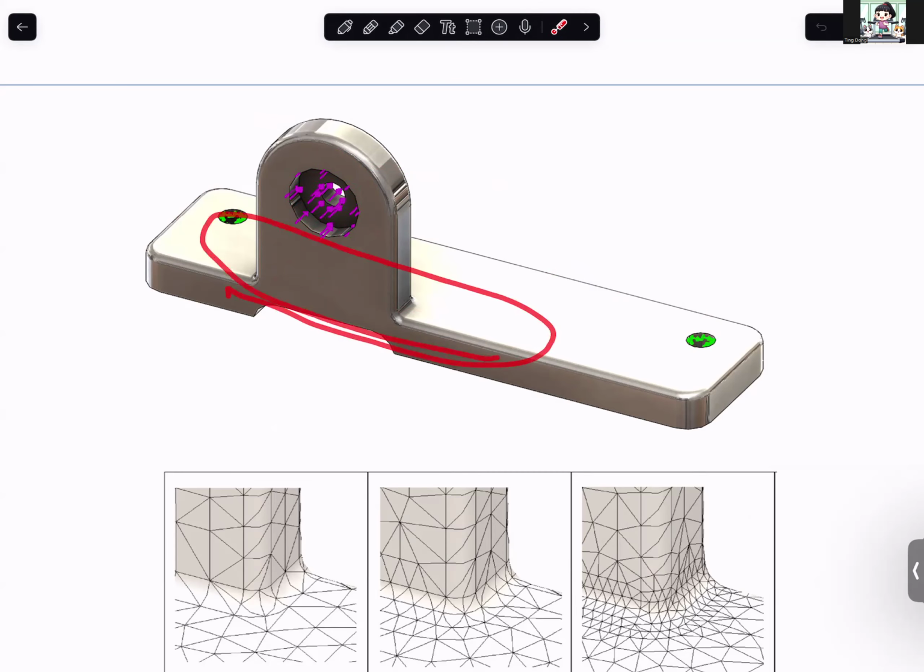This is a clamped base and the force is applied here. It will generate a bending, and this becomes the moment arm. Based on our understanding of mechanics of materials, we know that the maximum stress is probably around this area. One thing is that, for the bending moment generated by this force, as it goes downward, the bending moment increases and it's maximum here.